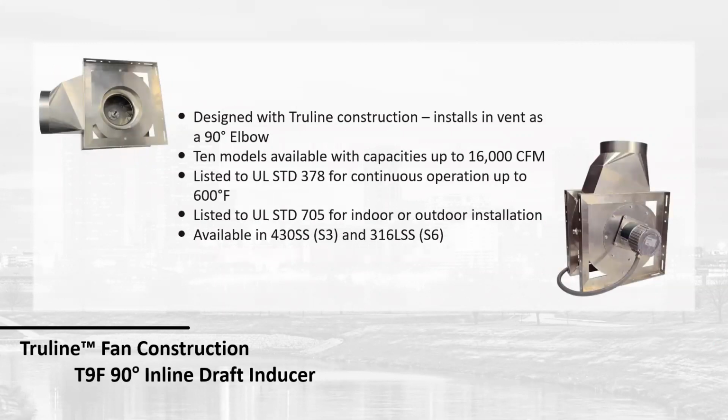Our 90-degree fan goes up to 16,000. Again, can be installed outside. One thing you might notice, and I'm not sure if you can see it through the screen here or not, but all of our inline products have drains welded from the factory. You don't have to modify the fan in any way, shape, or form to install drains. Again, condensate's very corrosive. It will eat through anything. Stainless steel, concrete, anything you put in its path, if it sits long enough, it will corrode that material away. So we want to get that condensate out to a neutralizer and then get it to drain as quickly as possible. So we provide drains on all of our inline products.